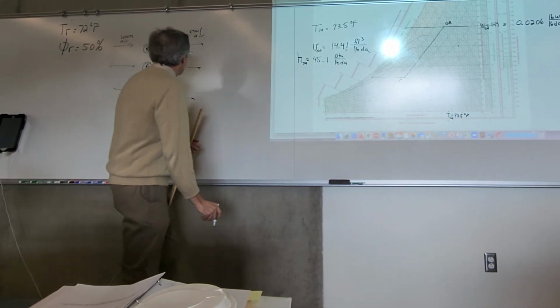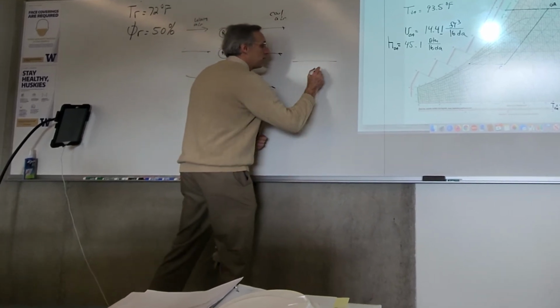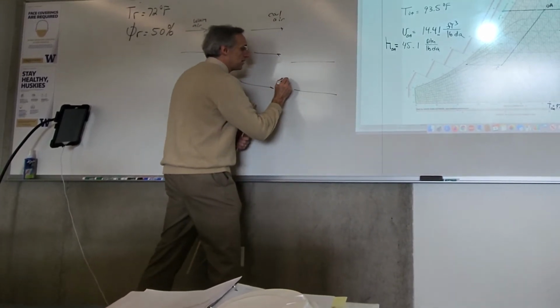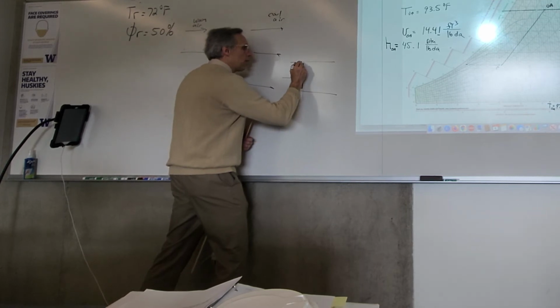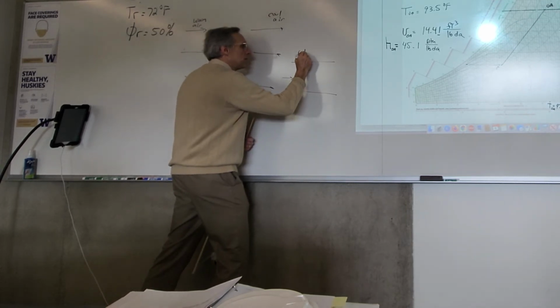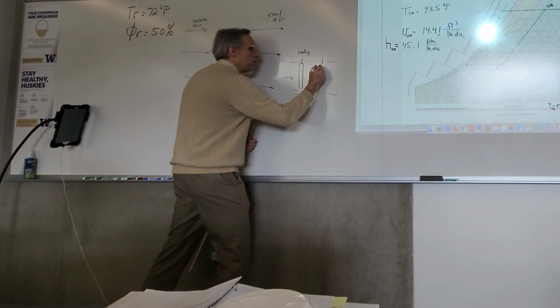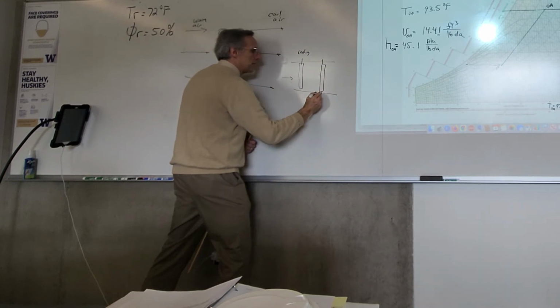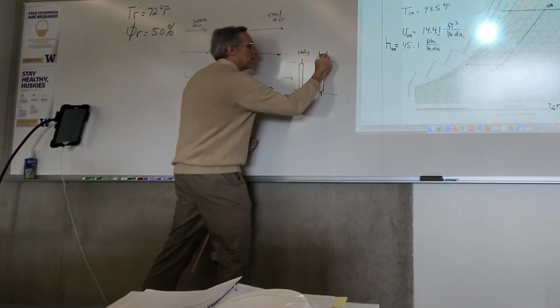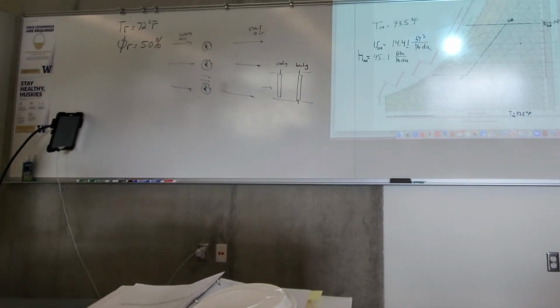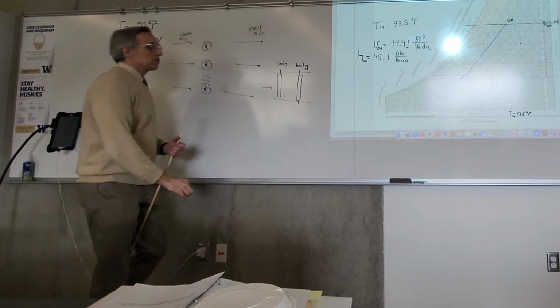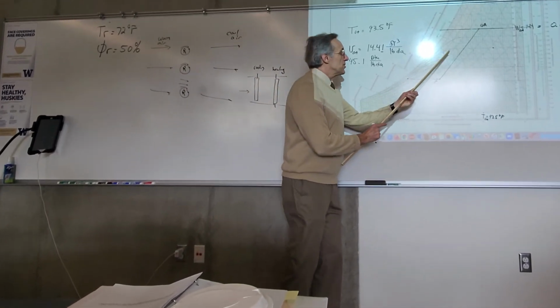So often air conditioning systems are actually designed with, there's your duct, there's your airflow, they'll have a cooling coil, and then there'll be a heating coil afterwards for reheating. This is dumb. It's just not a nice way to design a system, but that's what we would have to do in this case.